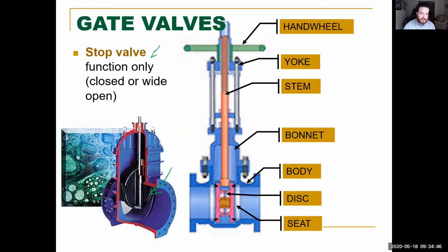All right. Because if it's wide open, the seat's still going to be getting worn down. The problem is when you have the disc. When it's fully open, that disc is all the way up in this cavity here. It's not going to be getting affected. But let's say this is the bottom of the disc, the thing that I just drew here. When water pressure is coming straight at it, think about it, this could be brine, a heavily salted, dense fluid.